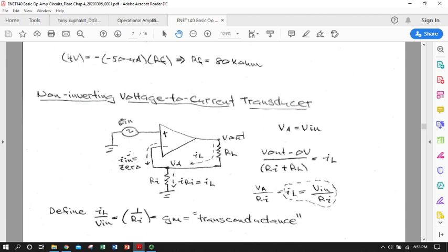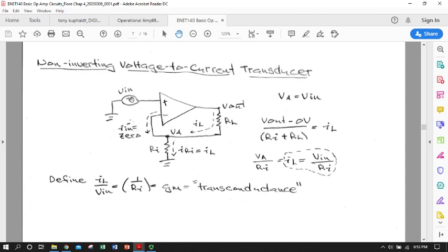So how do we get a gain expression? If I just express V sub in without reference to I sub L, I can't cancel it out. Well, lucky for us, we can quick draw that property of op amps that the potential at this terminal and this terminal are the same. Good for us. So V in is the same as V sub A because this potential is the same as that potential for an idealized op amp with negative feedback. Great. That makes it easy.